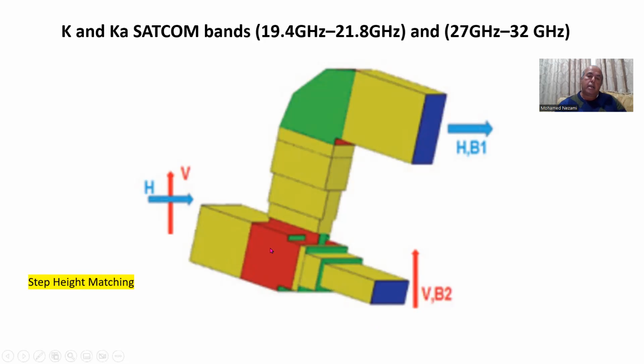And then your task is to design this piece here, okay? The piece that interfaces and matches the impedance from the square waveguide onto this rectangular waveguide. And likewise on the other side, to design a slot that couples the signal and then matches the impedance to this waveguide in here, which is the same as this.